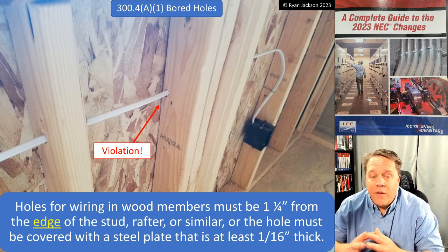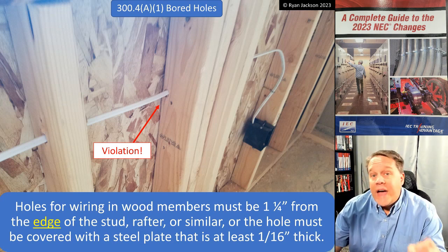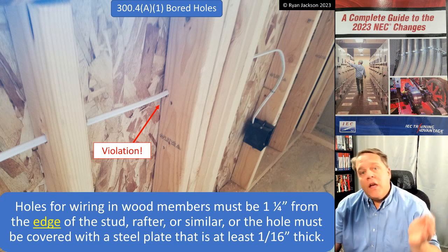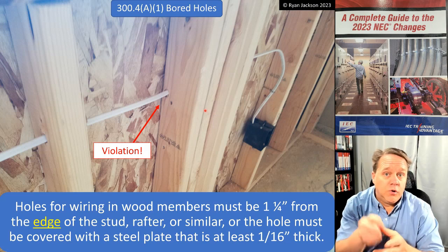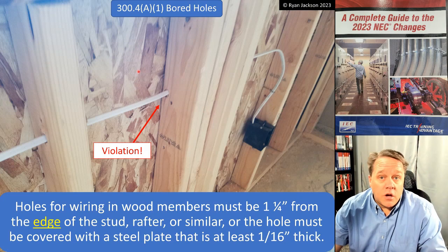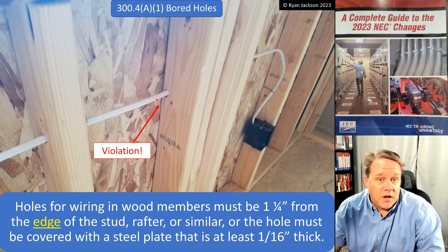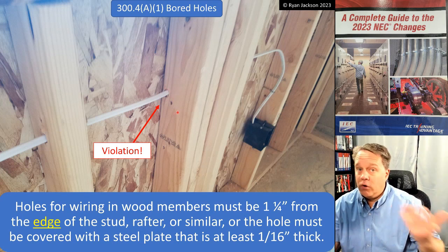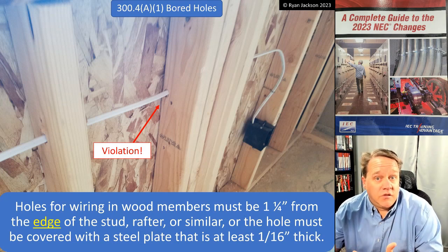And does it matter? Maybe a better word instead of face would be edge. So that's what they did. Now it's very clear that this installation is non-compliant. If I'm concerned about the drywall guy running drywall screws through my cable, I need to be equally concerned about the stucco installers putting staples through the back of my cable, through the back of the stud. So it doesn't matter if it's the front or back or face or whatever. Now it says the edge of the stud, which again I think is a nice clarification.